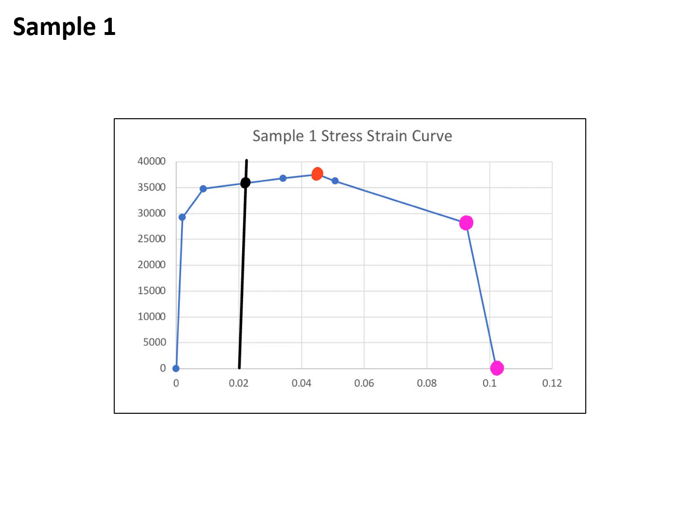By determining the stress and strain over time of the first sample, this stress over strain curve can be created, allowing us to find the different mechanical properties of the sample. For the graph, you'll notice there aren't a lot of data points given, and that is because when doing the tensile test, the grips moved at a very fast pace, so not a lot of data was able to be